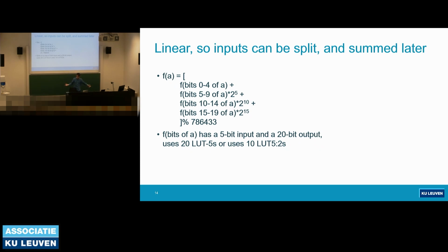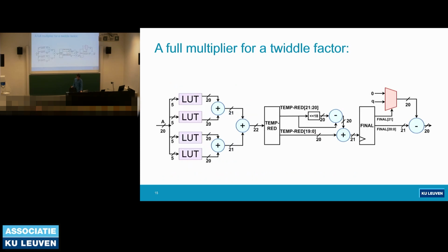And this gives you this whole function for only 20 lookup tables. Now, for the people not familiar with FPGAs, 20 lookup tables is very small. In fact, that's about the cost of just doing a multiplication, because when you do a multiplication, you also use these lookup tables. But now you've gotten the modular reduction for free, because you've calculated the reduction while you were doing the multiplication. And this is critical. You need 4 functions, so 40 lookup tables, and then you need to add all the results together.